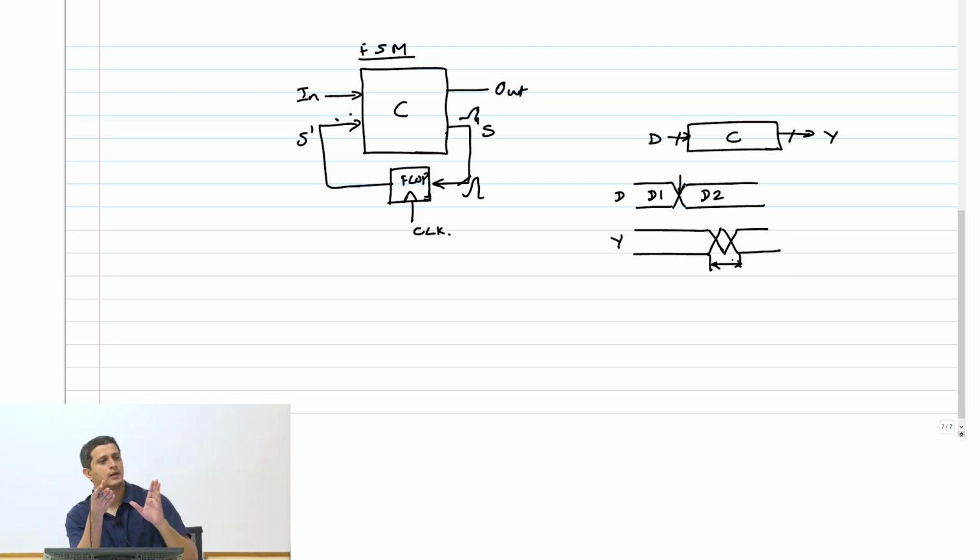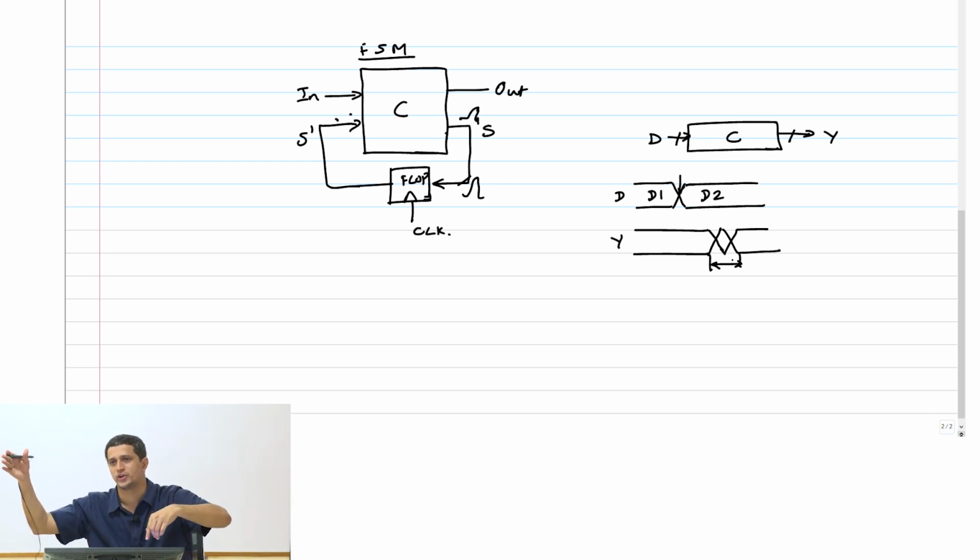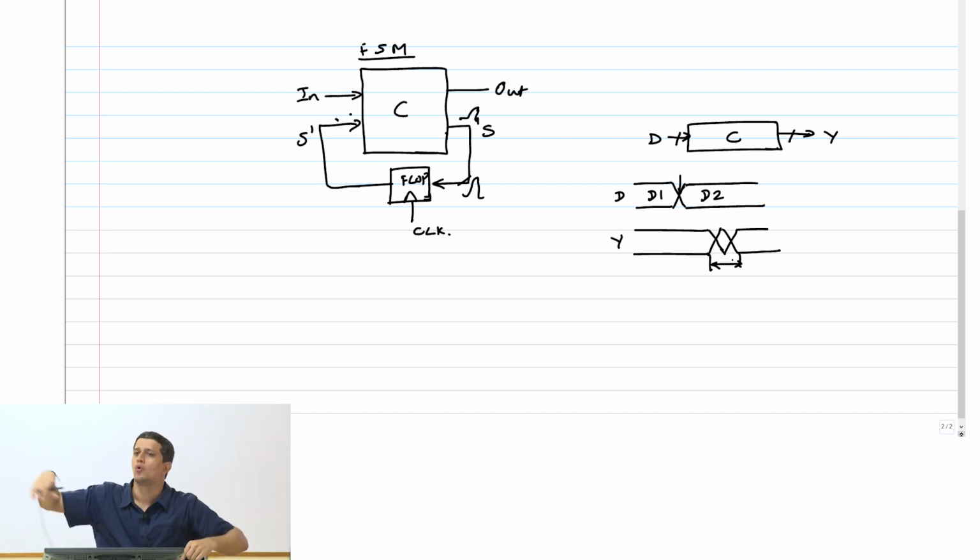For example, when one input changes, I could have some short path through my combinational block which causes one of the outputs to change. But now another input changes and it may come and overwrite this. There is a possibility that you'll have a glitch at one of the outputs, and that glitch is what we are capturing here. The issue is the glitch can affect the circuit going forward. So we have to make sure that the earliest change of data also we should be very careful about.